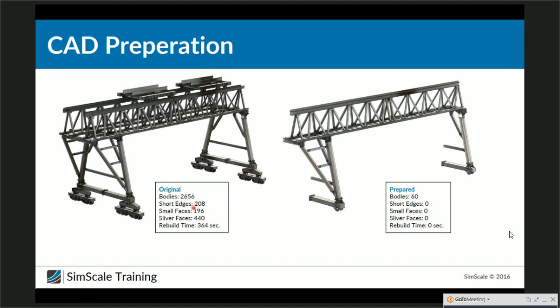Yes, there's just one thing I would like to talk with you before my colleague Krishna will take over and do a live demonstration of how to leverage SimScale FEA for Enduro Student India. And I will talk with you about something else which is very important, which we call CAD preparation. Because most of the time you need to spend as a simulation engineer to prepare the CAD model for simulation. I will just, as inspiration, show you some examples, and I hope that it will help you.